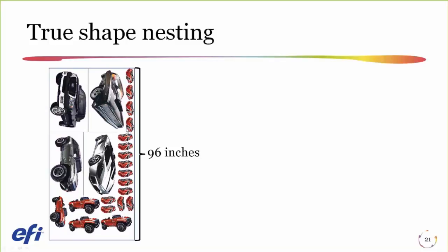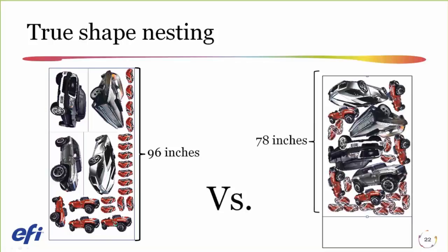Now, note the bounding boxes. We can honor bounding boxes, and all the other smaller cars are either vertical or horizontal. That's the 90-degree increments that we can rotate only. However, take a look at that same layout within the layout option. Boy, these guys are turned and twisted any which way and dropped in. I'm honoring cut paths. It just brings them together close to the cut paths. I don't have to worry about the bounding boxes. Look at all this media I've saved.